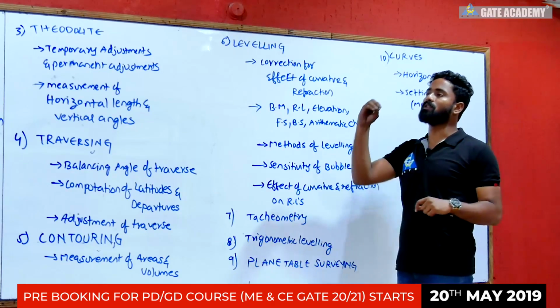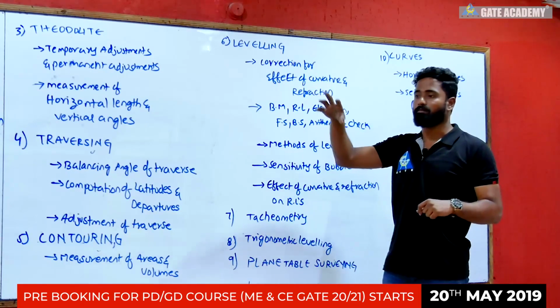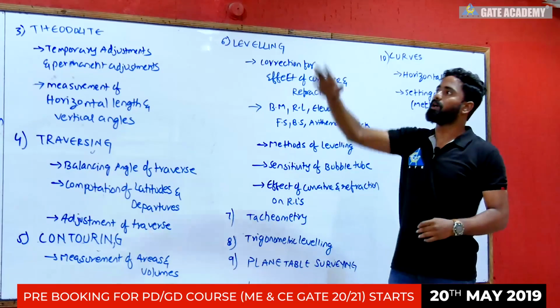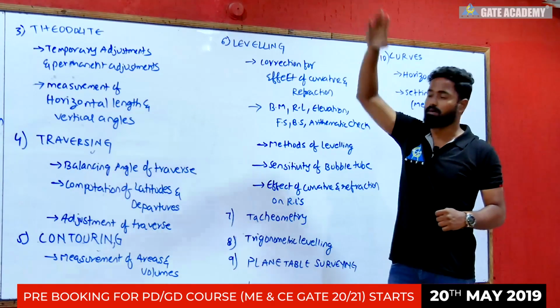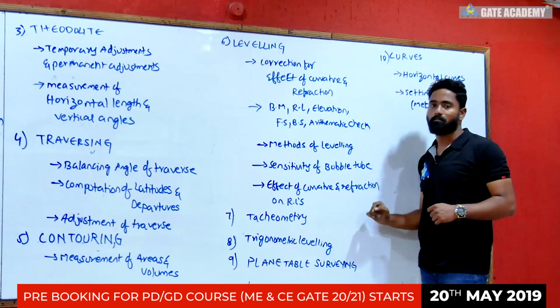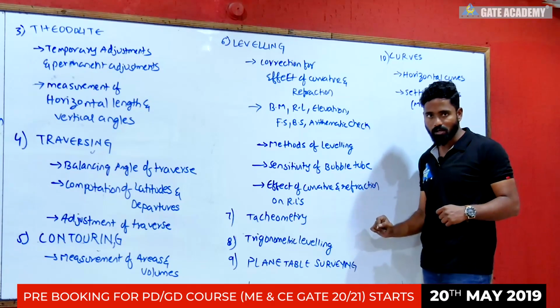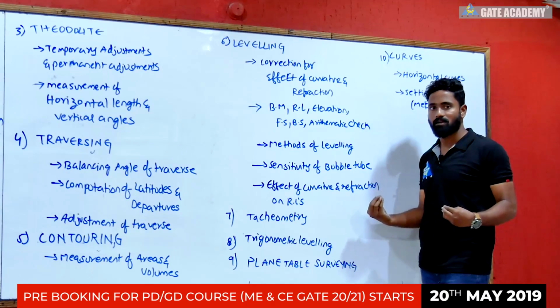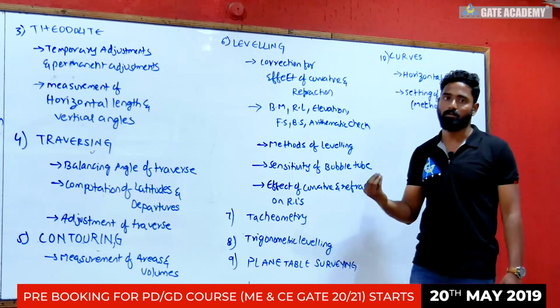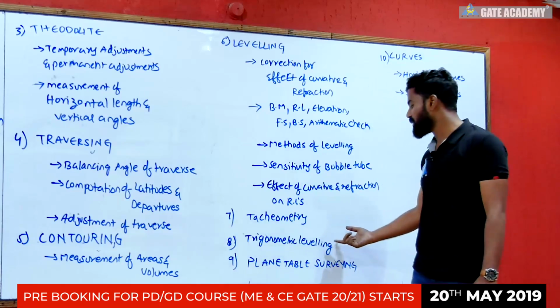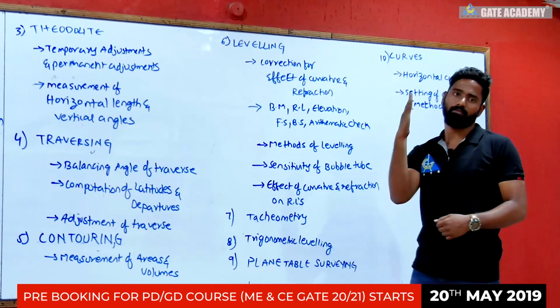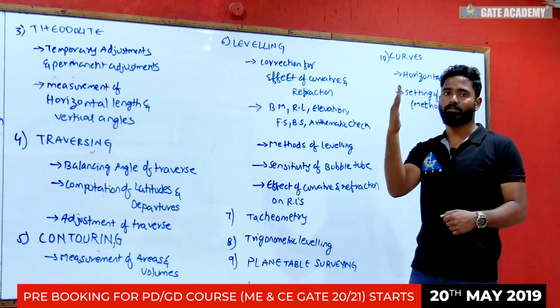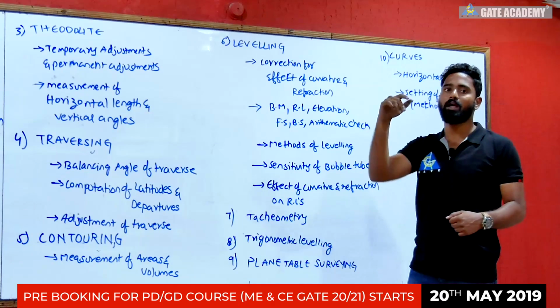Let us say I want the height of the church tower with respect to this one. You are here, it is somewhere on the top of the mountain. By using tachyometer and by applying trigonometrical laws, that is basic sine theta, tan theta, you will get the values of elevations. And here the different concepts would be staff kept normal, staff kept vertical,